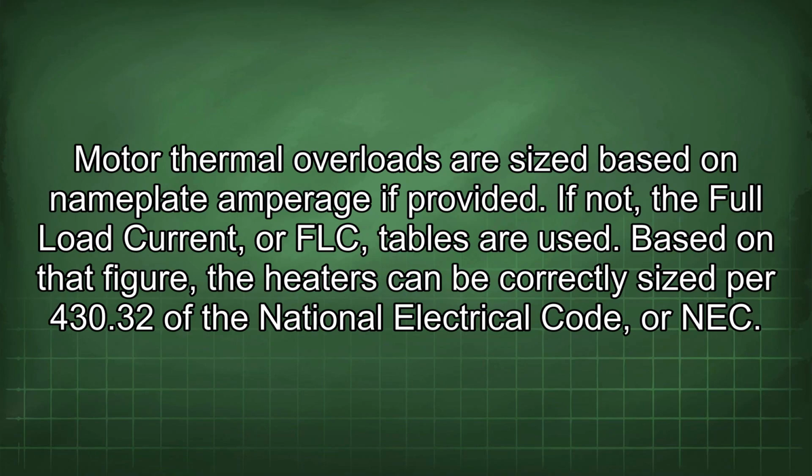Motor thermal overloads are sized based on nameplate amperage if provided. If not, the full load current, or FLC, tables are used. Based on that figure, the heaters can be correctly sized per 430.32 of the National Electrical Code, or NEC.